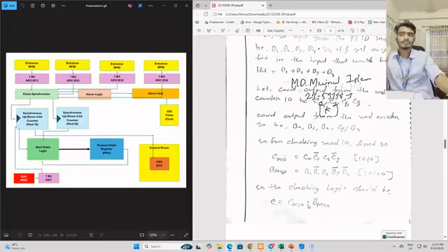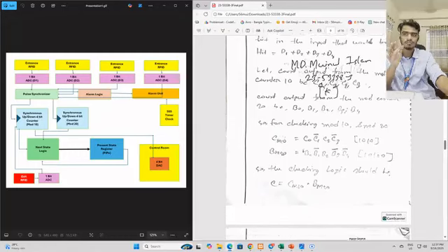If this check is complete, we can say the ticket counter has not exceeded 20, and the passenger count is not more than 20, so we can let the passenger in. So this C is actually our checking logic for the FSM.